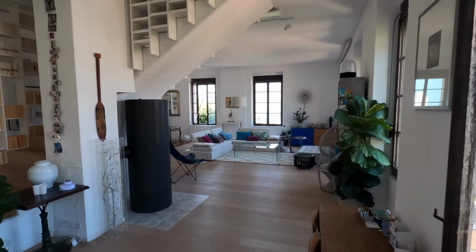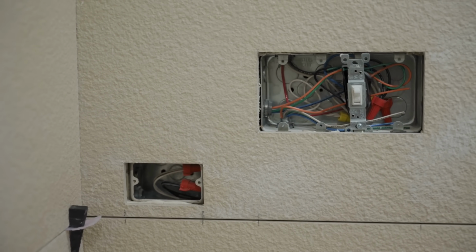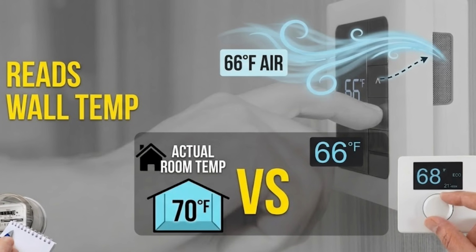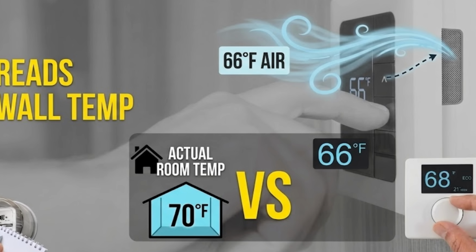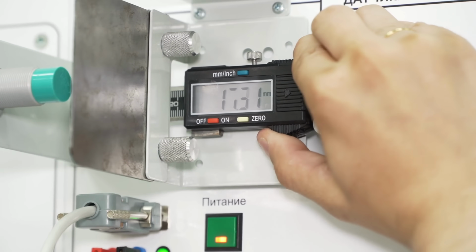Before we touch the buttons, we have to talk about the wall gap. Most thermostats are mounted over a hole in the drywall where the wires come through. That hole is a direct straw to the uninsulated air inside your walls. Your thermostat thinks your house is 66 degrees because it is breathing 66-degree air from the wall cavity, even if the room is at a perfect 70. The furnace keeps running because the sensor is being lied to by a physical draft.